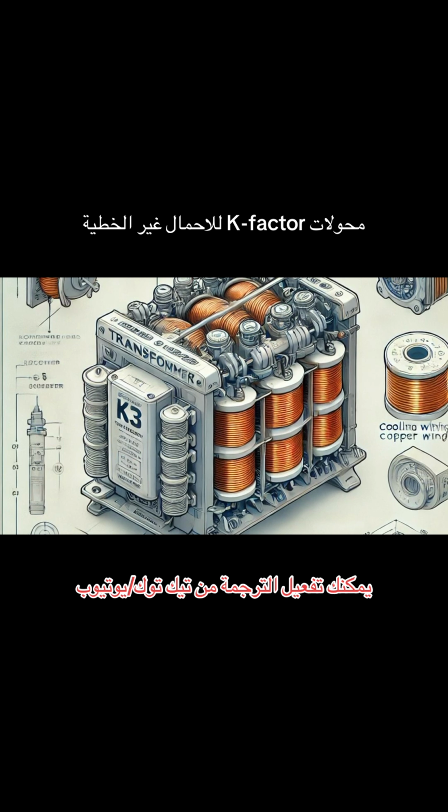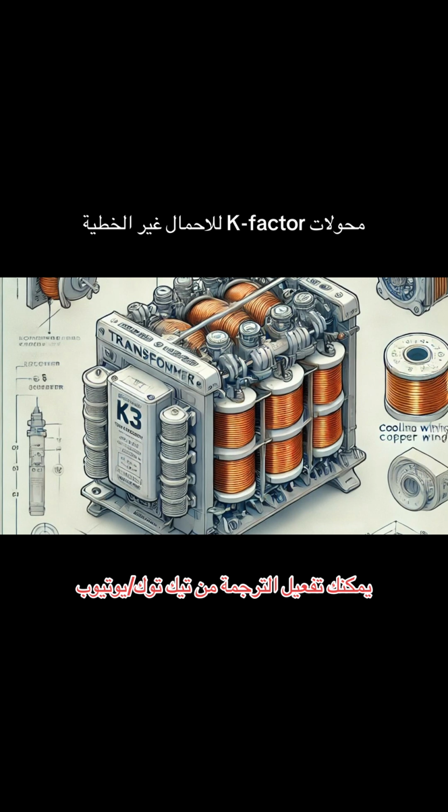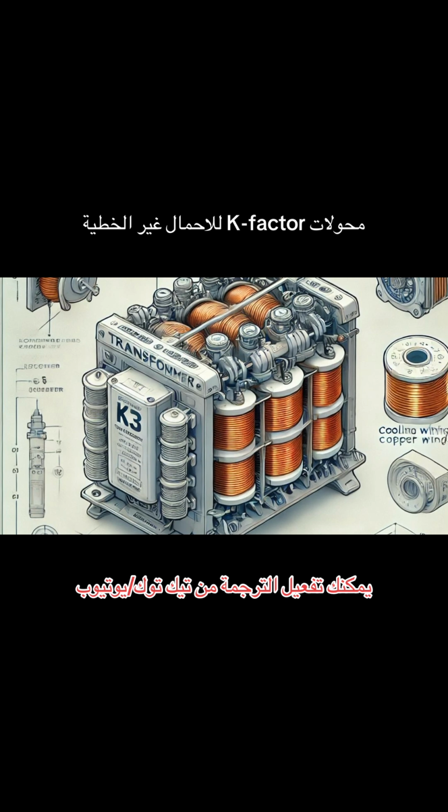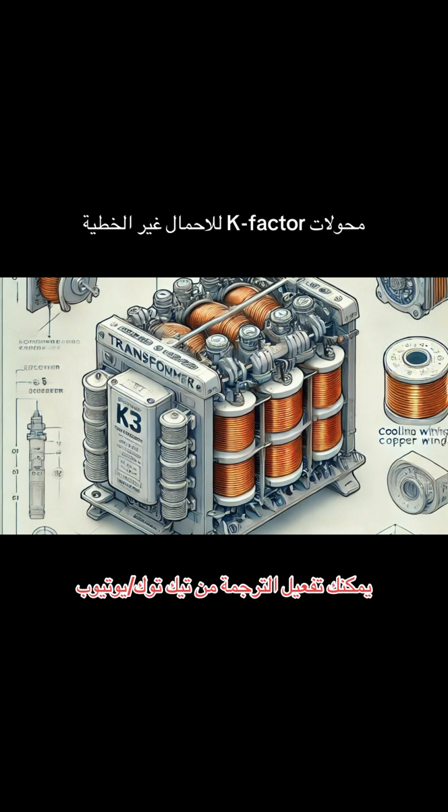So these added harmonic currents from all our modern gadgets lead to a significant buildup of heat. And it's not just in the neutral wires themselves, it's right at the transformer's connection points where the neutral comes in.